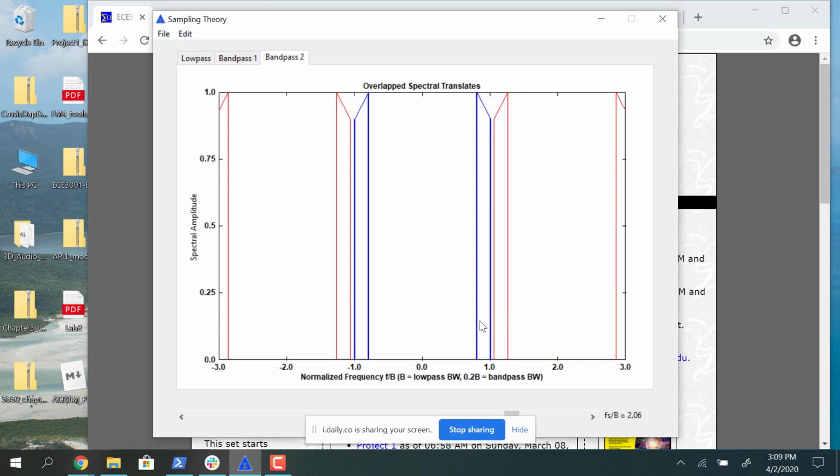And the other thing is, when we're sampling a bandpass signal, we eventually want to downconvert it, like in a coherent demodulator for double sideband. We want to downconvert it down to baseband or close to baseband. So problem number 6 is investigating some of the issues behind that and how a software-defined radio purposefully undersamples, because the bandwidth of the signal, which I'm pointing my arrow at right now, is much less than the highest frequency that we're trying to capture.